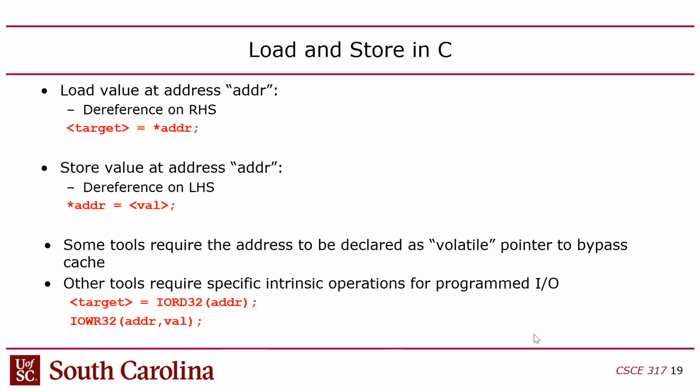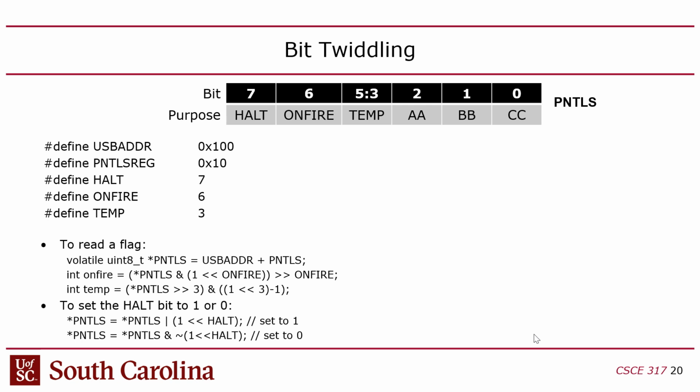Now Arduino just uses a plain old dereference, right? Which is why when we originally developed this course, we were developing it with Arduinos in mind. But if you're using a more sophisticated processor, you may have to use an intrinsic for these programmed I/O operations, okay? Now, generally, like I said, you guys usually don't ever see these because they're buried in the driver code, right? But if you don't have an operating system, then you have to become aware of this. So you have to look it up.